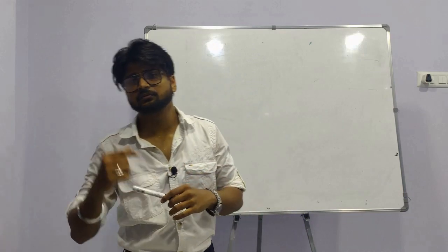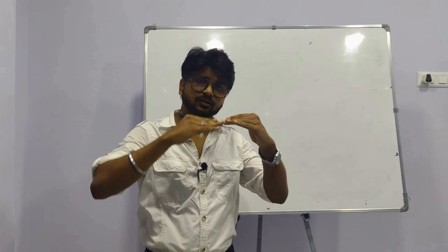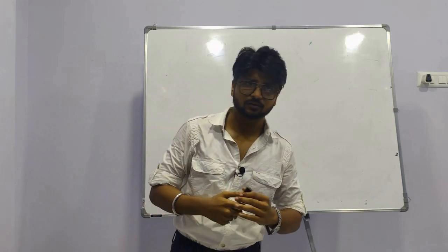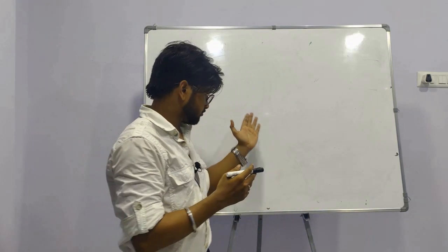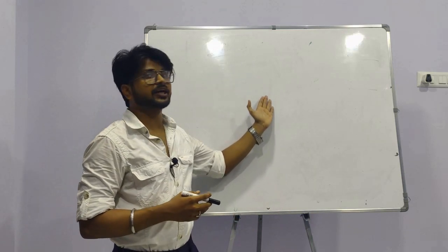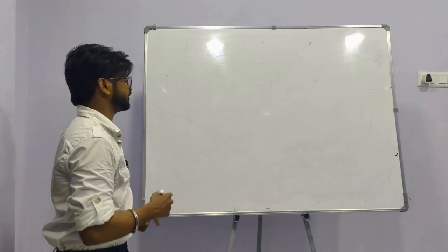As I showed in the diagram, the arrow mark through the RL is connected to the center of the secondary winding of the transformer, which is really very difficult. So to overcome that, in the field of electronics, the bridge full wave rectifier is constructed. So let us see the diagram.